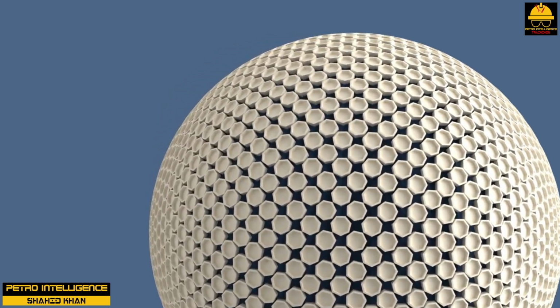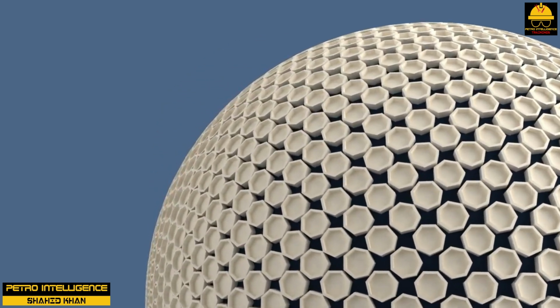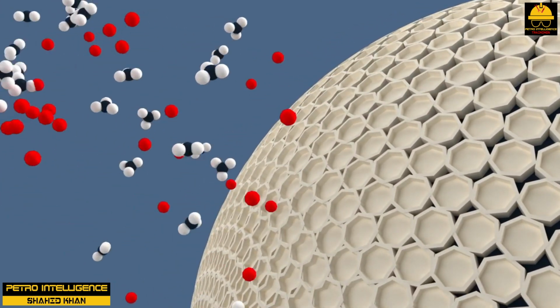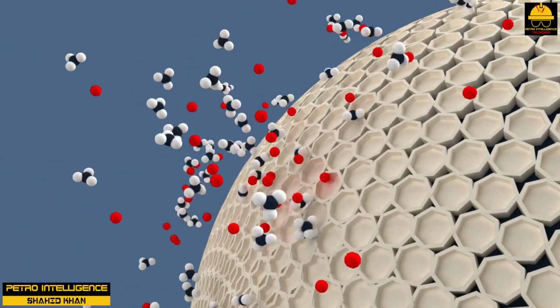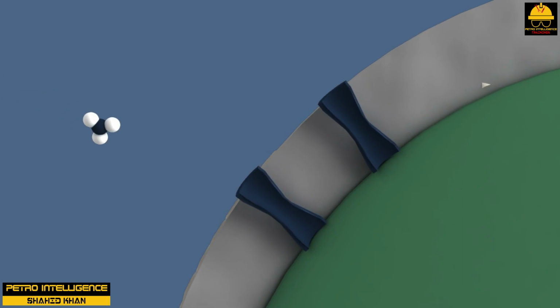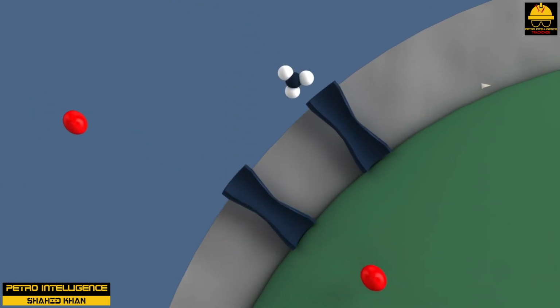Molecular sieves. Molecular sieves are an example of a different type of adsorption process. The sieves are small, porous solids containing submicroscopic holes. These holes are actually about the size of an individual molecule. Some molecules will fit inside these holes; other molecules, because of their size or shape, will not. One application is the removal of traces of water from an organic chemical stream. The relatively small water molecule will fit inside the pores while the bulkier organic molecule will not.